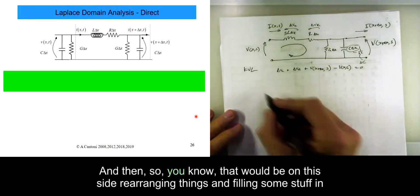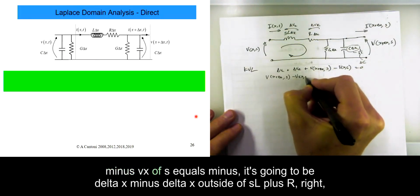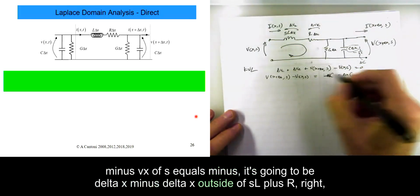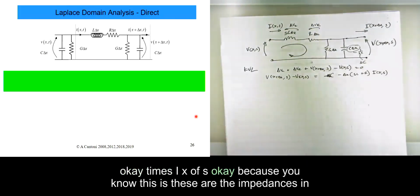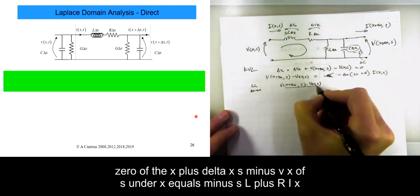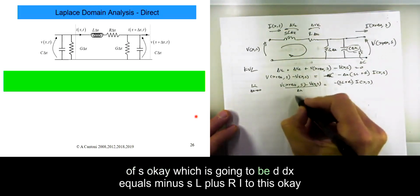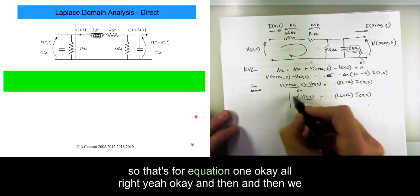Rearranging things and filling some stuff in, minus Vx of s equals minus delta x times (sL plus R) times Ix of s, because these are the impedances in the Laplace domain. Then in the limit as delta x tends to 0, Vx plus delta x of s minus Vx of s over delta x equals minus (sL plus R) Ix of s, which is dV/dx equals minus (sL plus R) Ix of s. So that's equation 1.